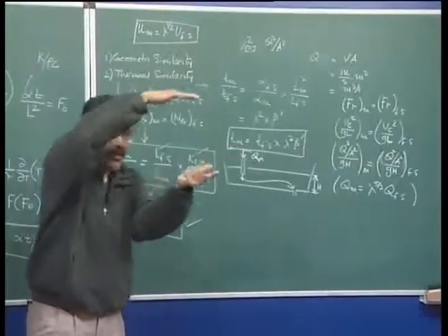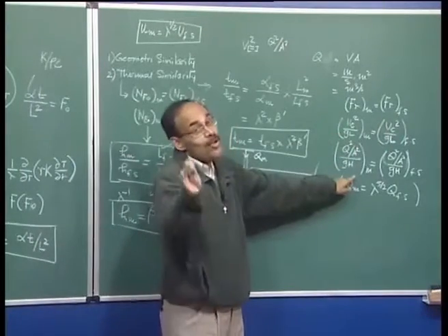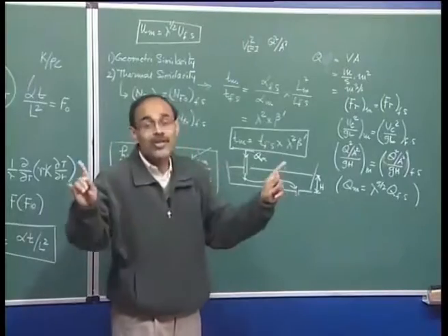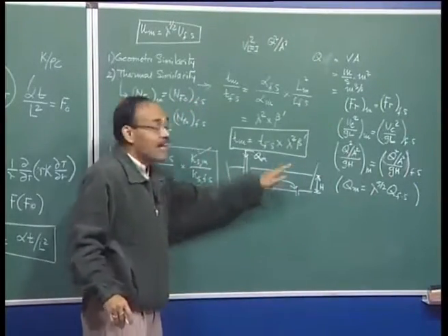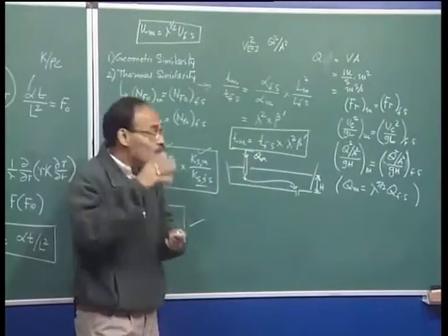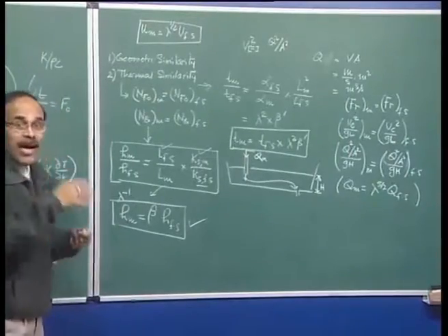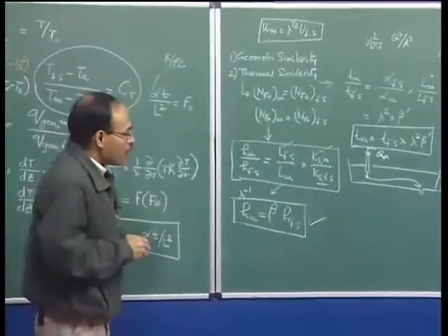So, we have considered the Navier-Stokes equation, and this is the limiting form because we have ignored Reynolds number. Now, we have to consider no boundary condition for the Navier-Stokes equation, because boundary conditions are all alike in the full scale and in the model system. To derive the thermal similarity criteria, now I visit the thermal balance equation, and I have to consider the boundary conditions.